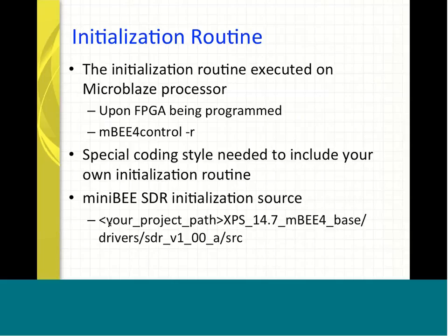So these reset signals are not generated as a hardware reset. We actually generate a software reset, if you will. It's like you have a PC and you try to reboot it, so it will go through the initialization routine that's executed on the MicroBlaze soft processor. That's the reset routine that's going to be executed when you initialize the FPGA.